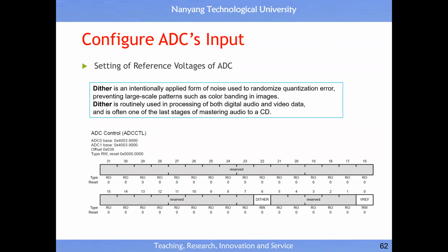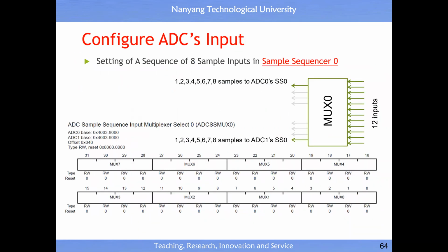So if you add in the noise, it will actually eventually stabilize the output reading. Whether you want to add in noise or not, you just decide here. Putting bit 1 here means the reference voltage is always 3.3, but with a little bit of noise added in, to compensate for environmental noise, etc. So that is this.